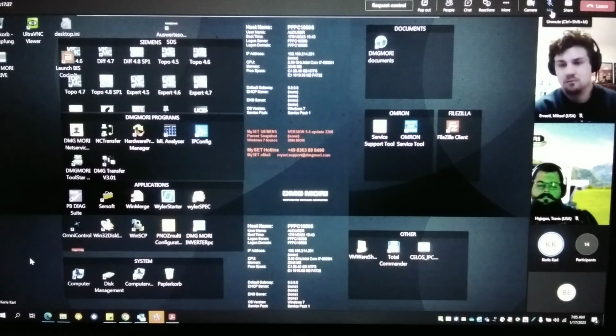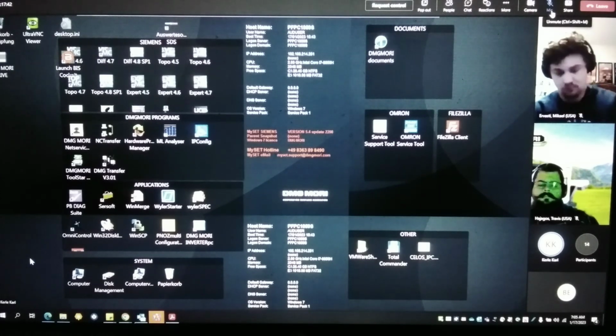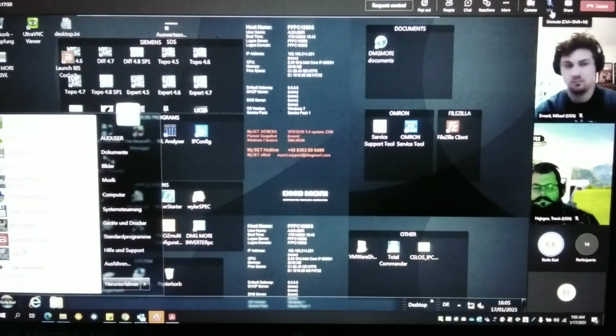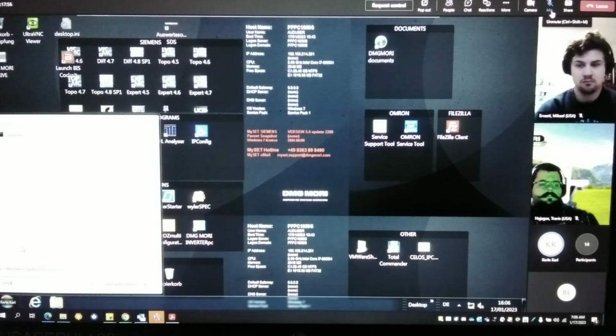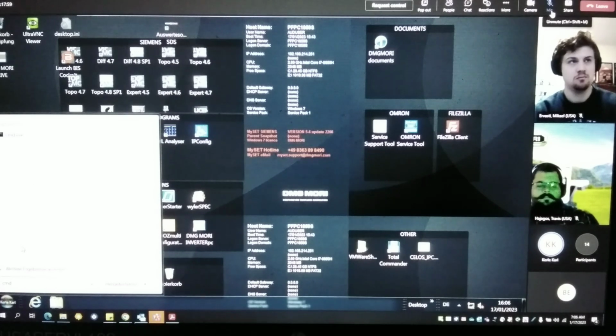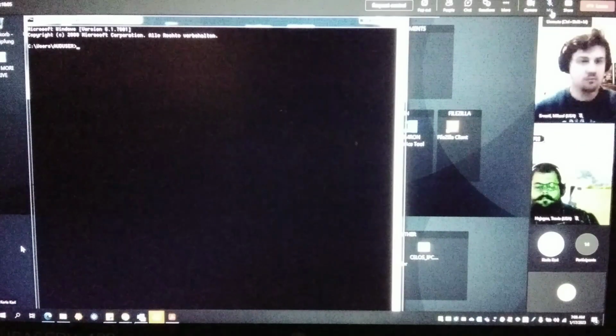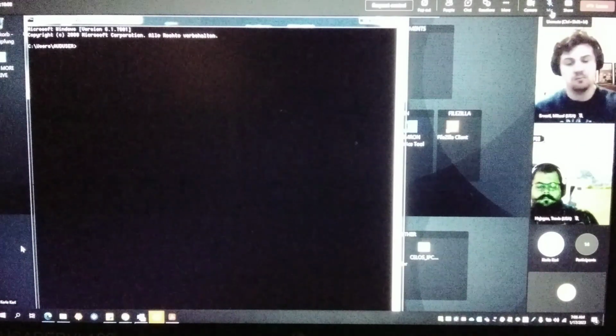But sometimes we have also the situation that the actually used IP address of the communication processor is different from the value you wrote in a config menu window, okay? To escape such a fault, I always try to open the start menu like I do now, and immediately I type CMD. So here you see on the top a light blue highlighted cmd.exe. You type the command cmd, hit the enter button, and your Windows shell box opens.